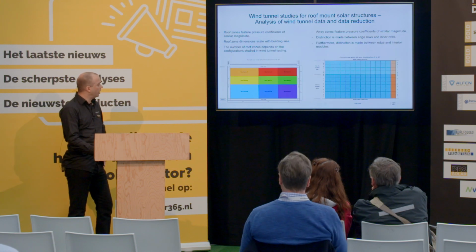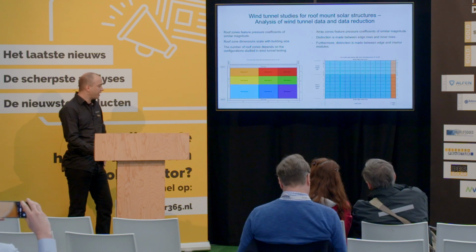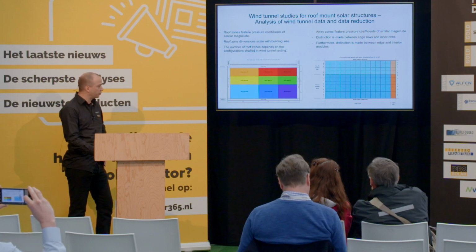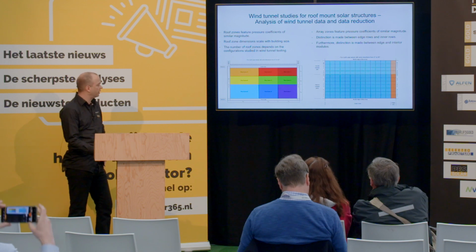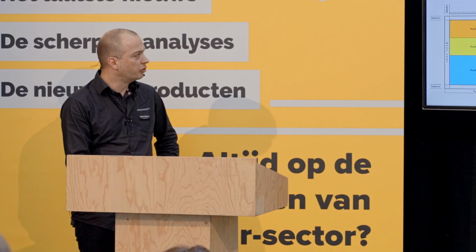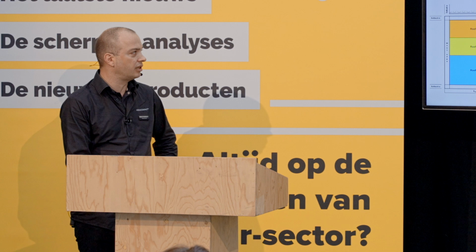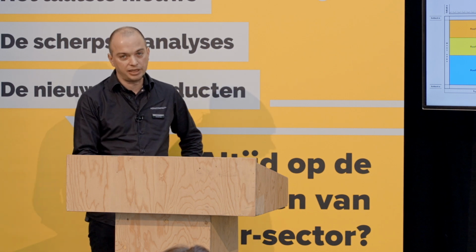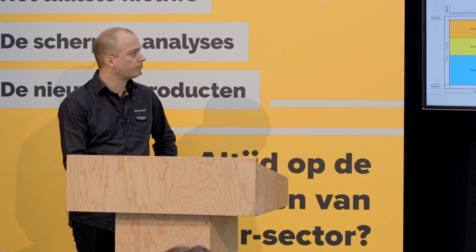With regard to roof zoning, if we test for 9 different positions on the roof, we will come up with 9 different zones. But of course, we do that to capture all the relevant flow effects. The roof zone sizes must also scale with building size. They are not constant.